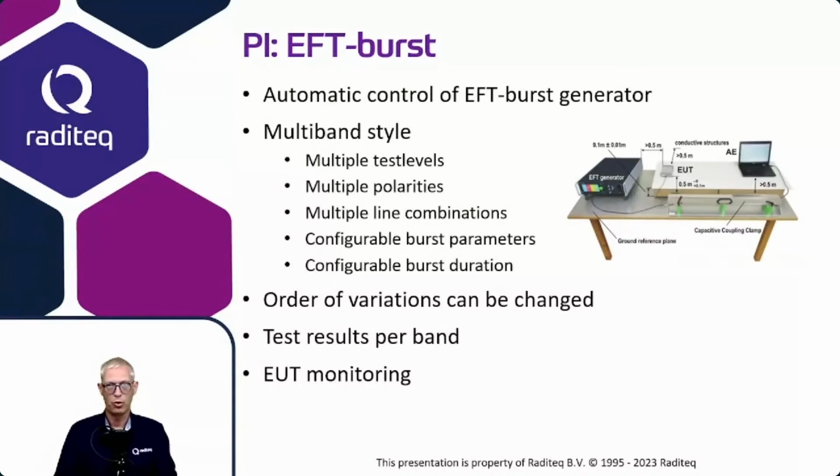Then we also support the EFT-burst test, and this is an automated test again, so RadiMation is able to control the EFT-burst generator. And this is also done in a multi-band style. So multiple bands can be configured with multiple test levels. Positive discharge, negative discharge can be configured. Different line combinations can be configured. And all the parameters of the burst can also be configured.